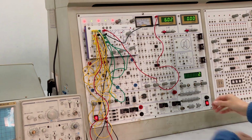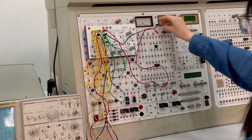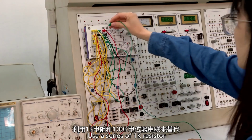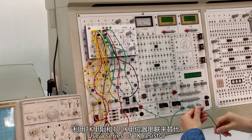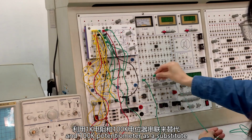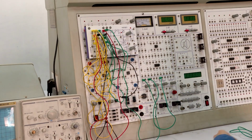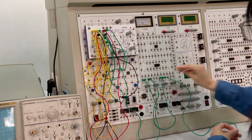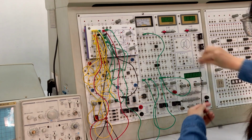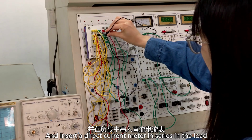Recheck the circuit. If normal, connect the load at the output and use a series of 1K resistor and 100K potentiometer as a substitute. And insert a direct current meter in series in the load.